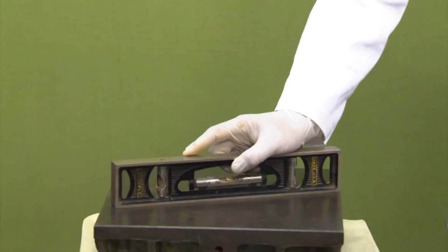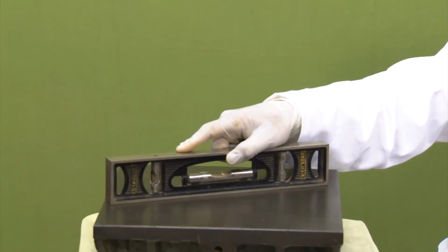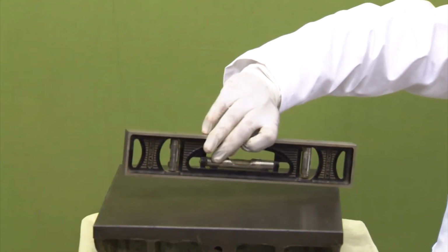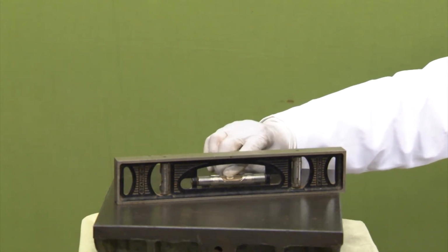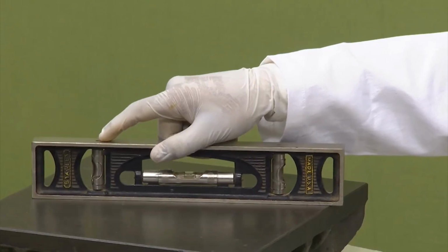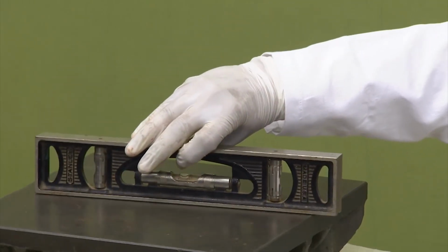So, this is the spirit level. Another precaution or guideline for the spirit level is that whenever we need to use it, we can check the level in this direction, and also we turn it 180 degree to check if the position of the bubble changes. So, this will tell us whether the spirit level, this instrument, is properly calibrated or not. Okay. This was one thing.